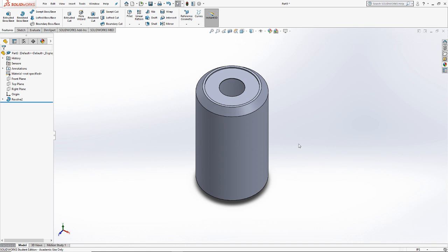So you have three options for doing that type of extrusion. One of them is very labor intensive, but gives you a ton of control. The other two are shortcuts, each of which has their advantages and disadvantages. The advantage of using the thin-walled feature within the revolved extrusion is that you have a very quick and easy solution. It's also easy numerically because it doesn't have to try to keep track of all of those additional lines. The downside is you don't have as much control as you do with the offset tool within the sketch. The downside there is now you have twice as many lines to deal with.